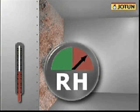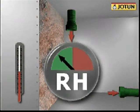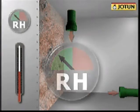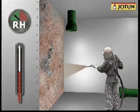If the relative humidity is higher than specified, it's essential to install a good ventilation system. Always have the inlet at the top and the outlet at the bottom, as solvents are heavier than air and will collect at the bottom.